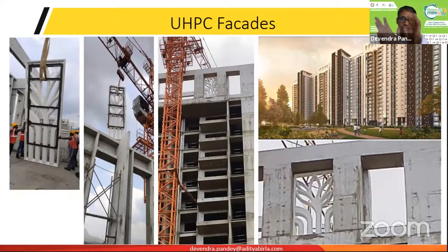The last material which I'm presenting here is ultra high performance concrete, used for aesthetics, used for thin panels. This concrete has strength as high as 150 MPa, which allows us to cast it into very thin panels, and as a result reduce the dead load on these panels. And because it's concrete, these panels are fireproof, lightweight and durable.